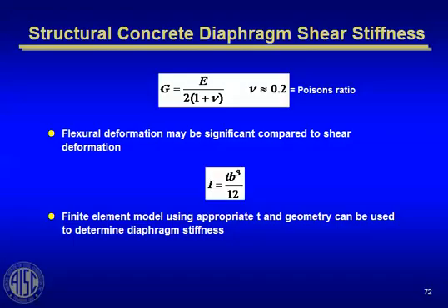What is the definition of that shear modulus term G we talked about? Well, remember it's E over 2 times the quantity 1 plus Poisson's ratio. G prime is equal to that G term times the thickness of the deck. That's a fundamental property of a metal deck, the G prime term that you see tabulated in the catalog. And as I say, usually the shear deformations control over the flexural deformations simply because the decks are so deep in their own plane.